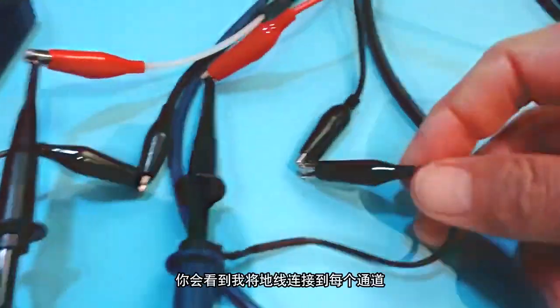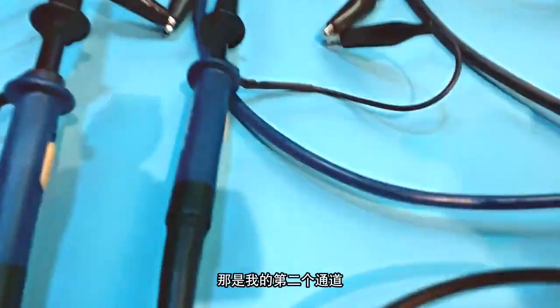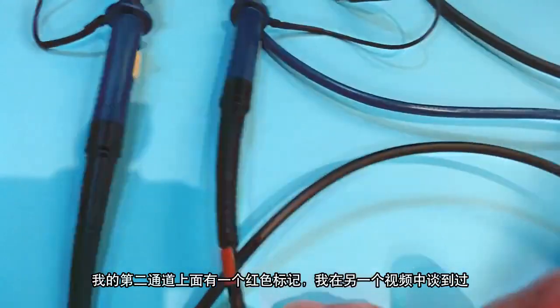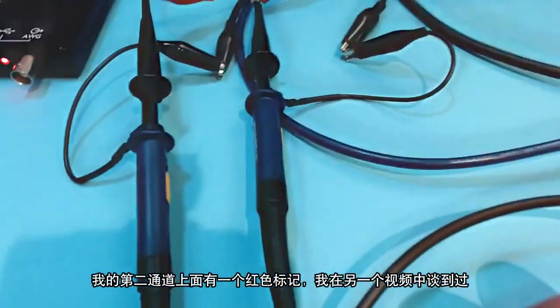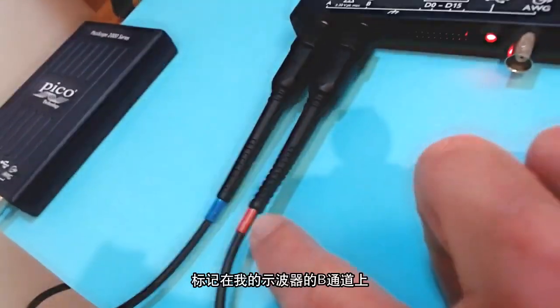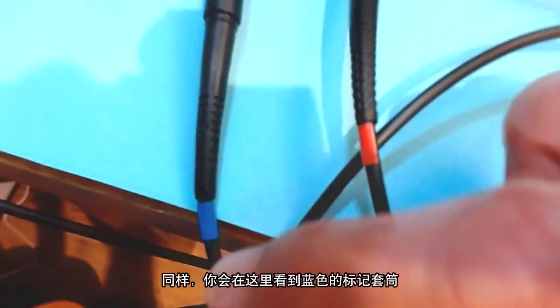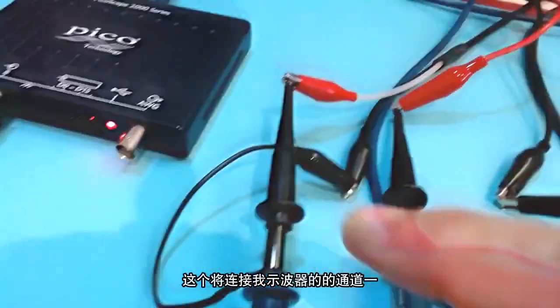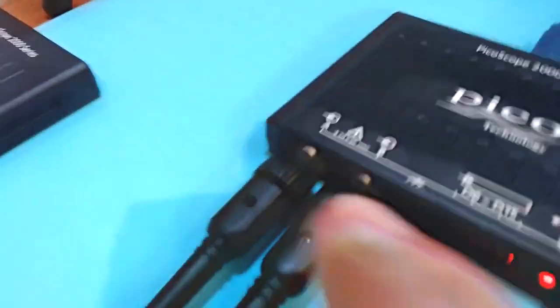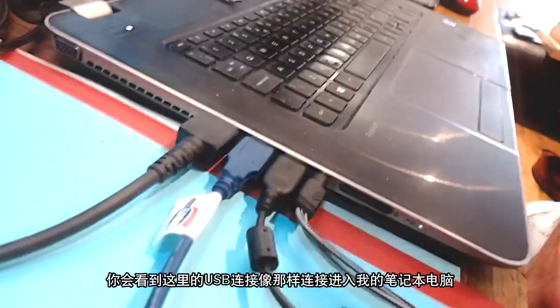Let's see, they come out and they go into my scope probes, and you'll notice that I've connected the ground leads to each channel. So there's my channel 2, which has got a red sleeve marker on it, which I talk about in the other video associated with scope probes. And equally, you'll see the red marker sleeve on channel B of my signal generator. And similarly, you'll see the blue marker sleeve here, and that's going to channel 1 of my scope, and that's going to channel A on the signal generator. And so you'll see the USB connection here going through and into my laptop like that.